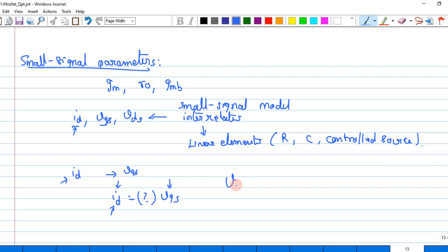I write the composite signal in terms of the DC as well as the AC signal, and again I can express the composite signal of the total current in terms of the capital ID plus the small id. Okay, so are you clear with the differences between all of these three terms across VGS and ID? Do you have any doubt in it?